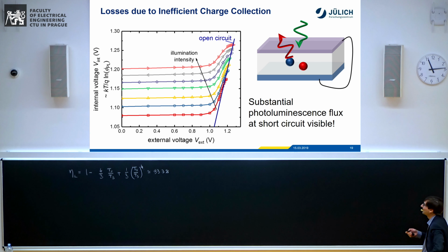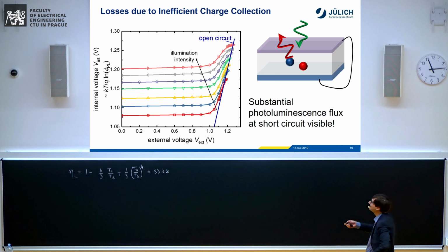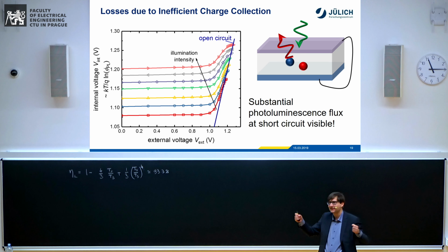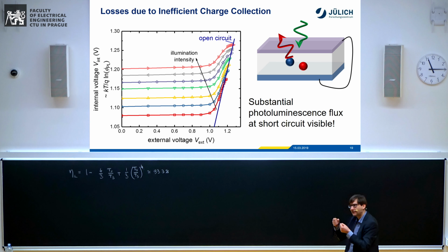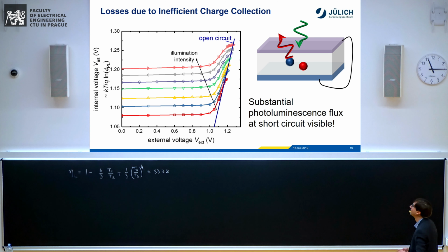So okay, this graph's now a bit more complicated. So this thing here is an estimate for the quasi-Fermi level splitting as a function of voltage. And it's calculated just by taking kT/q times ln of the photoluminescence. Yeah? And you do that on a device, you connect it to a Keithley and change the voltage. Yeah? And then step by step measure the photoluminescence.